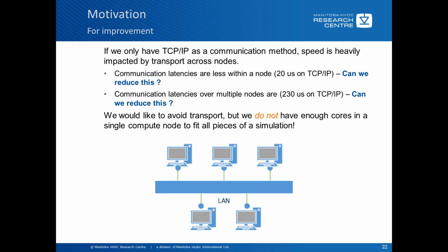And if we want to have 20 or 30 or 40, it's more difficult to find computers that can carry that number of CPUs, and certainly at a high clock speed you won't find that. So we want to be able to spread the simulation across 4 computers or maybe more computers that have large numbers of cores per node. And then we can break systems into much larger and much smaller pieces of granularity, so we can handle much larger systems as well.